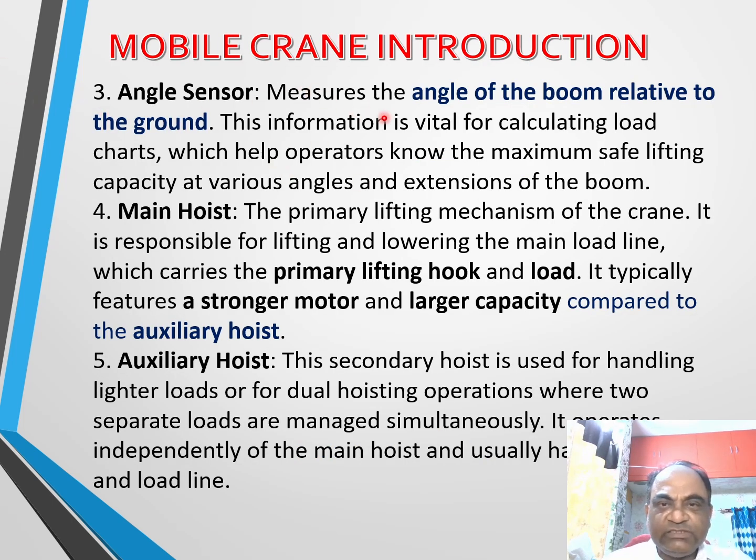Angle sensor, and this measures the angle of the boom relative to the ground. And this information is vital for calculating the load chart, which helps the operator to know the maximum safe lifting capacity at various angles and extension of the boom that can be done.